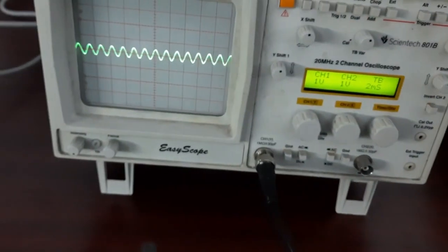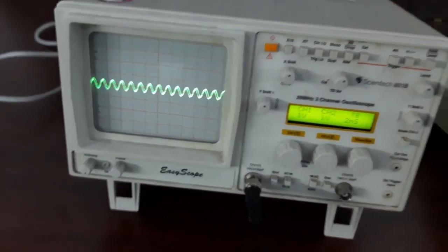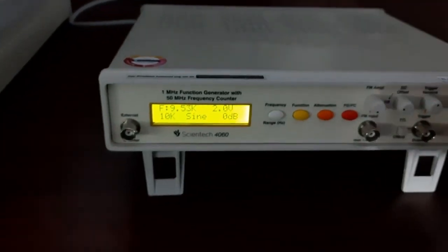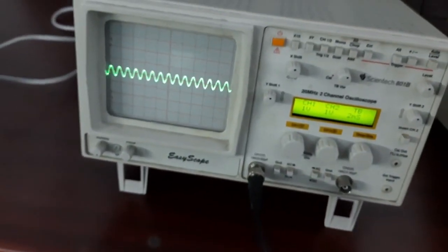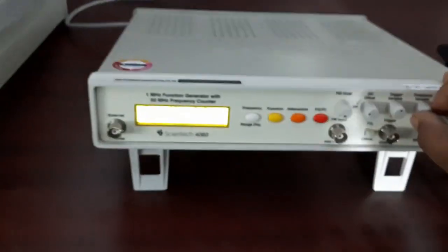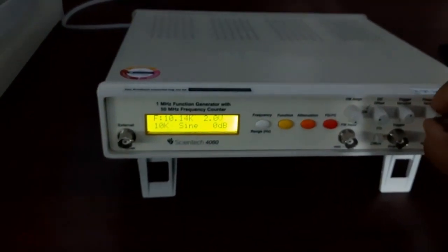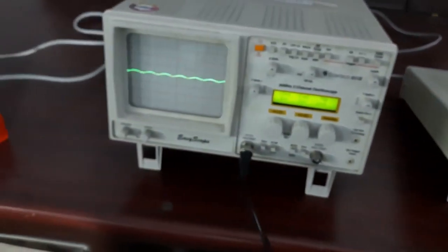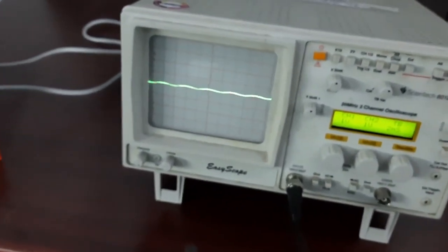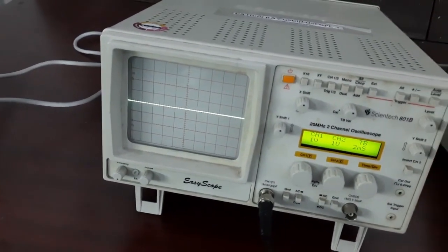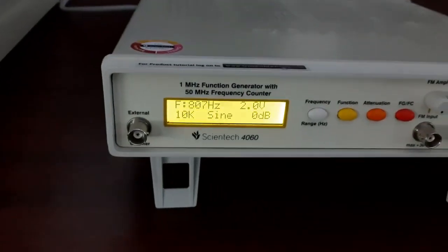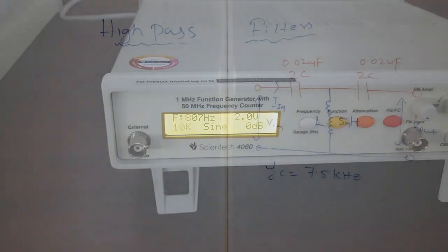So at 9.53 kilohertz, we can see there is output coming through the high pass filter, because it's a high frequency wave. Now again, you can see 10k also it is giving us values. On 10k it is also high frequency. Now if I decrease it again, you can see it is now showing us no output, because it is again on low frequency. At again 803 Hz, 807, we have no output on the CRO.